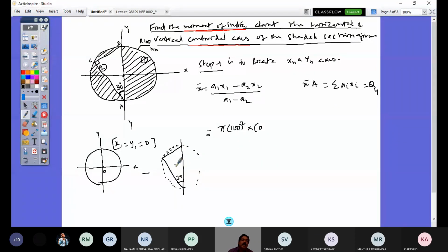So for this, what is my x2, y2? How do I locate? I require to locate with respect to its centroidal axis. So this is my y-axis, and I have it here. My centroidal axis is along this height, at 1/3 of the height. So somewhere here is going to be my yg2 axis for the second one. What is my xg2 axis? So I have it here. This is my reference given xy. So from here, where is it located on this? How do I get it?